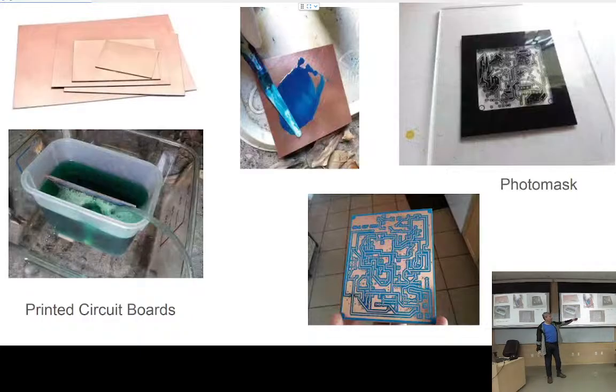Normally for the actual tracks we use this photomask scheme, but if we want to put the names of the components on the board, then we sometimes use silkscreen for that. At least the name stuck. I don't know if a current board is actually made with silkscreen, but normally when you describe the layers to make a printed circuit board, you have a layer that's called the silkscreen, which is just informative parts.